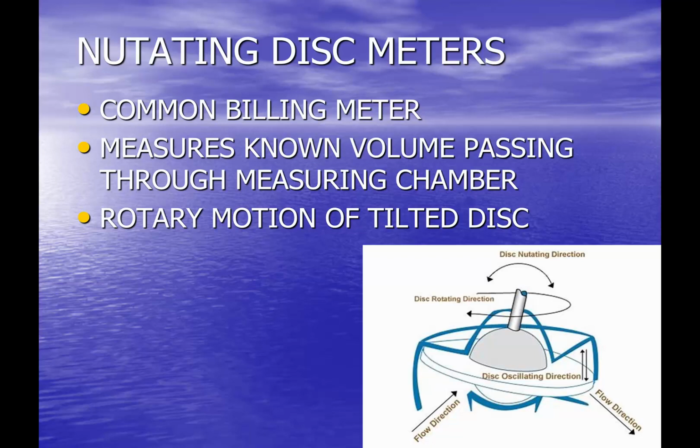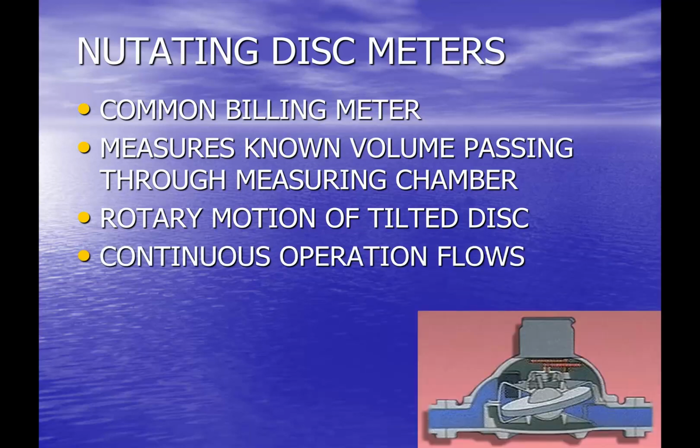That's how the water passes through the chamber, the metering chamber, which again, the important thing here is, much like we talked about with pumping applications, where you're pumping the entire volume of a pumping chamber, in that case, it was a kind of constant as you cycle through it. In this case, it's basically the same concept. You have a constant volume that as it goes through, you rotate the disc and you're reading the meter, ultimately generating a read on the meter.